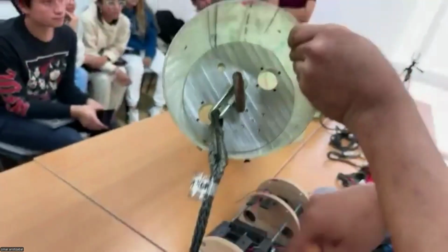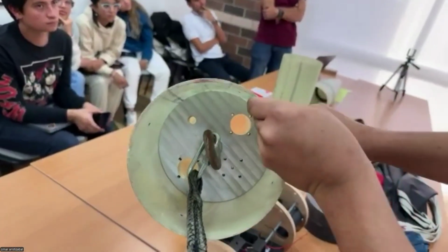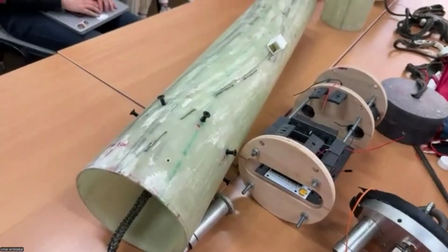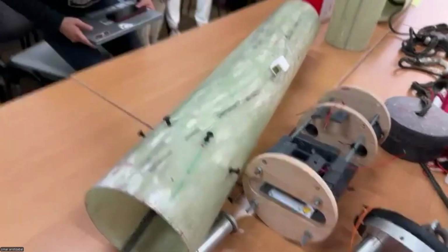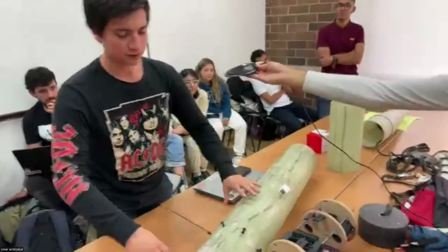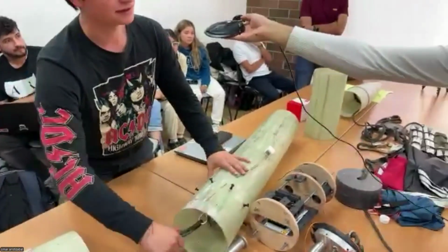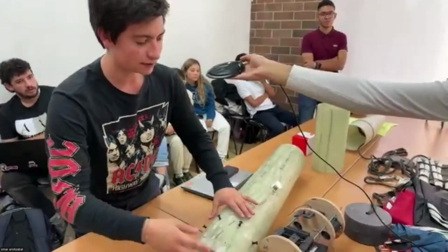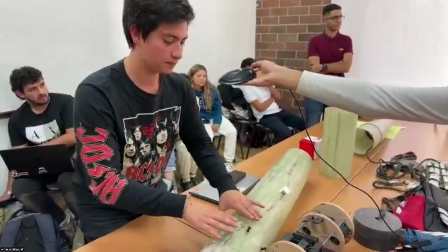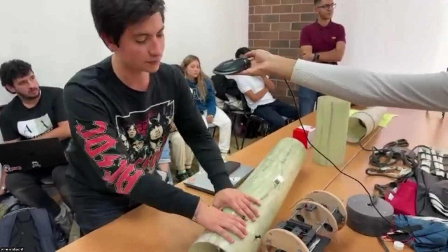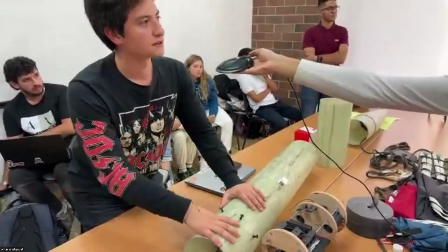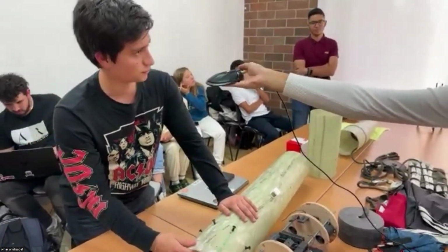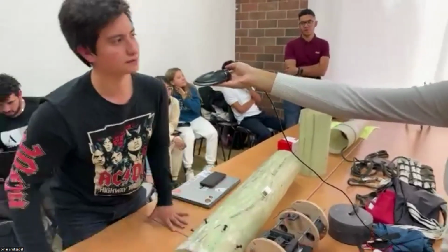And have you performed the shear analysis on those screws? Yeah, all the shear analysis of the screws was done. Maybe you want to expand a little on that. We basically performed an analysis where the shock cord is loaded, and we insert a force into the eyebolt, and this force is transferred via the screws to the airframe. All was checked out, and I think it has a safety factor of 3, but yeah, it's checked.